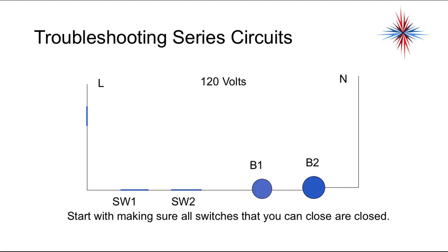So again, let's go back to our series circuit. To troubleshoot a series circuit, start by making sure all switches that you can close are closed.